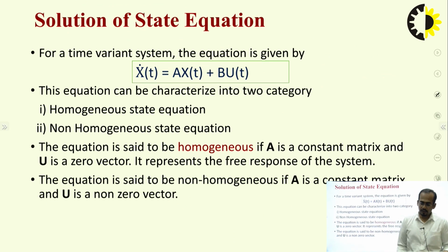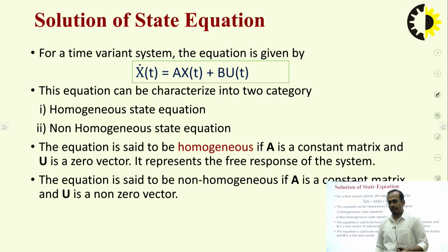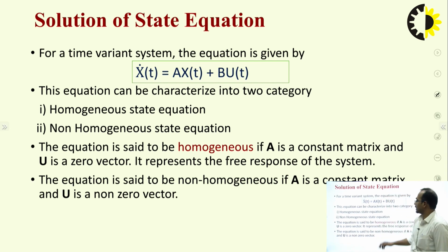Now coming to the next topic, that is the solution of a state equation. As I have already told you, this is the state equation x dot t is equal to Ax(t) plus Bu(t). This is the time invariant system, and the equation can be characterized into two categories. First is the homogeneous state equation and second is the non-homogeneous state equation.